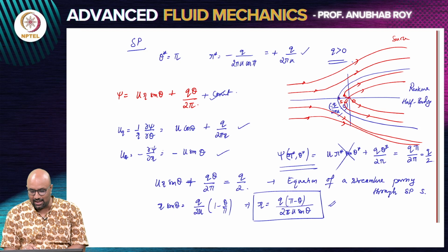Once you superpose the two, qualitatively you would expect that the uniform flow will get deflected by the source, and the source also would not be able to move in all directions radially outwards. That too would have streamlines bending due to the uniform flow. That's a qualitative picture. When we did this formally, we saw a streamline pattern where you now have a stagnation point.